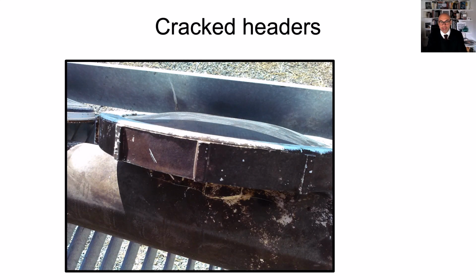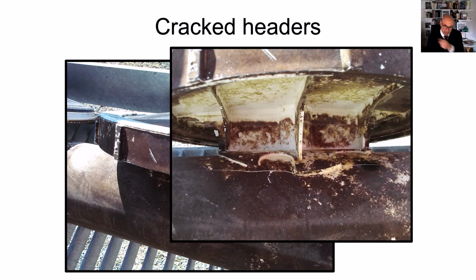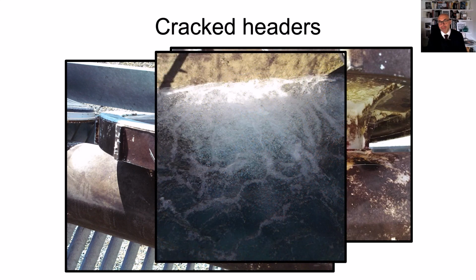And what could these cracks be? You see that airline fracture below that pipe? It looks innocuous. You can barely tell it's there when you're looking at the pipe without water. That's a line there, that's the fracture there. But when the pipe is in the water, you see there's a big swell and all the air wants to come out there because it's the point of least resistance. So the air doesn't really come out from the diffusers anymore.